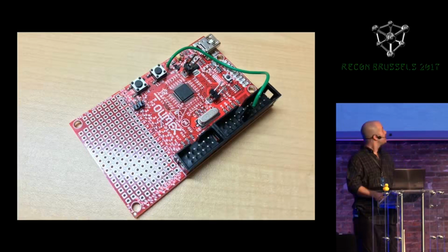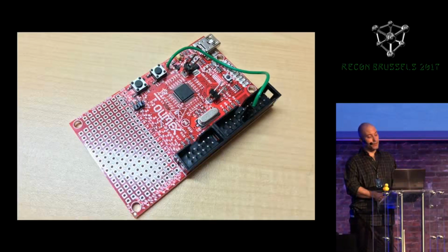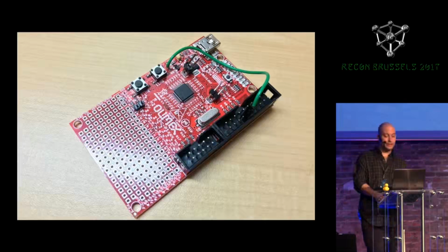And then also I've added this green wire, and this green wire is just connected between the ground pin on the debug port and the VBus signal going into the chip, because normally this development board is designed so that you'll be using the USB bootloader. So in order to disable the USB bootloader, I've added this green wire, which is simply holding the VBus pin low. So we'll enter the serial bootloader instead.